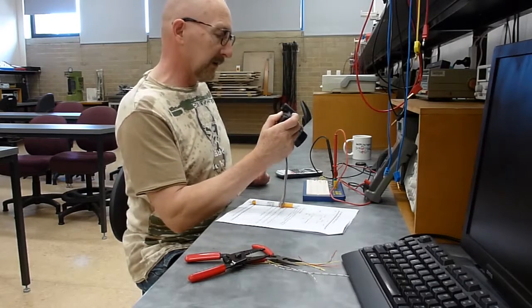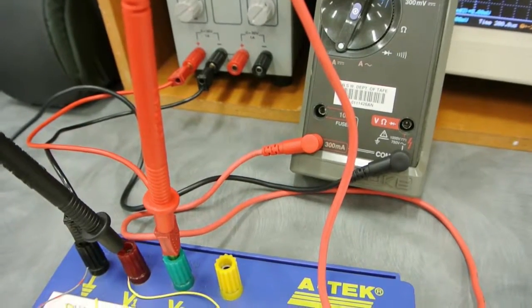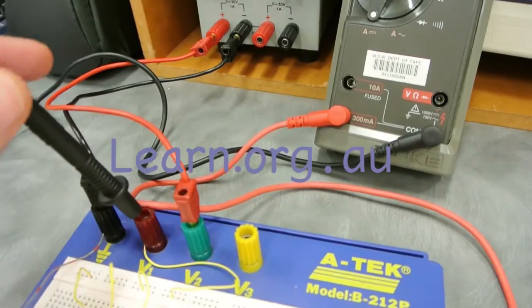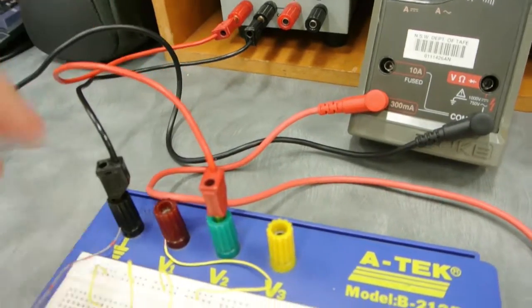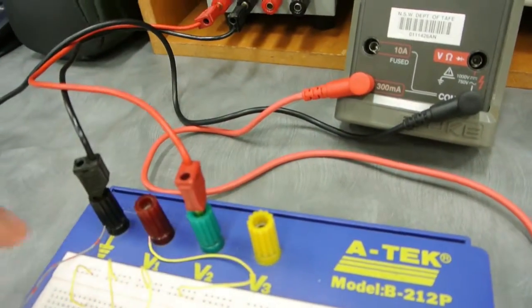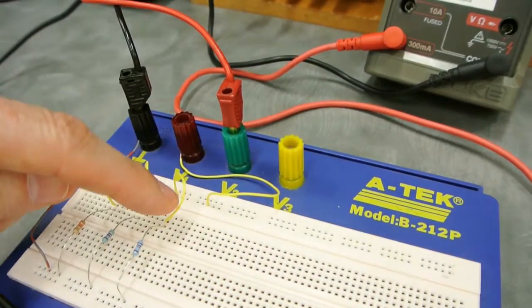Be careful when you're measuring the current. It's really vital that you think about how you're going to set up the meter. When you're setting up the meter, you have to actually break the circuit. So what I've done here, I'll just unwrap this. I've taken the 9 volt power from the power supply and put it to a blank terminal on my board, and this is the terminal that goes into my circuit.